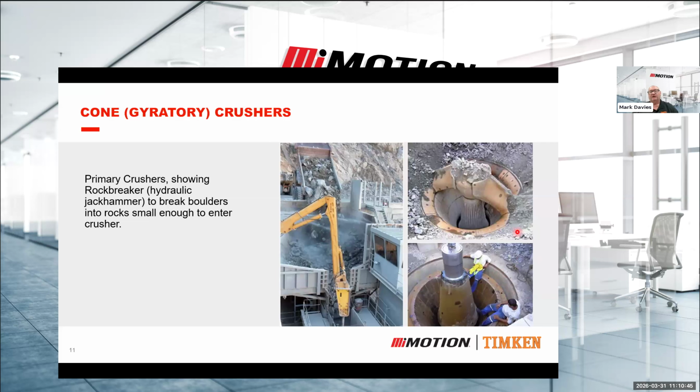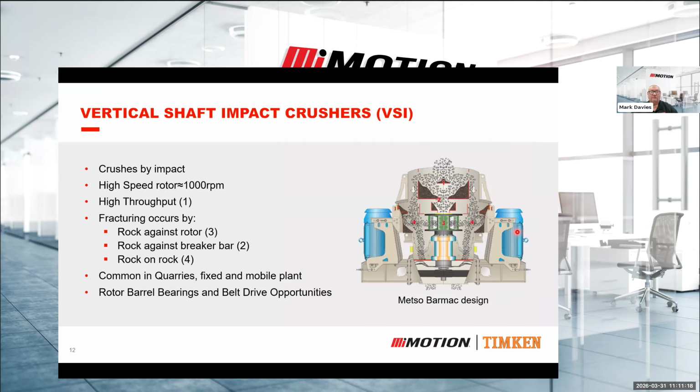Commonly, if it's used as a primary crusher, it's actually used as a multi-stage. So there's more than one crusher sitting on top of the other, two or three, which then gives that much more consistent output once it goes through all three stages. It's not as common. Some very, very large mines like iron ore mines will have these, but certainly not particularly common in hard rock and certainly not in the quarry systems. Yeah, you won't see those.